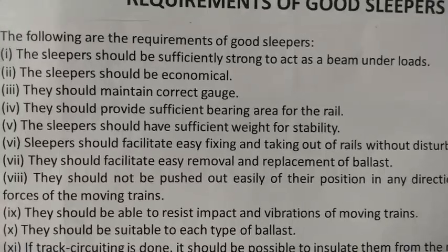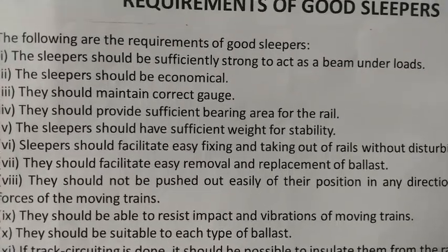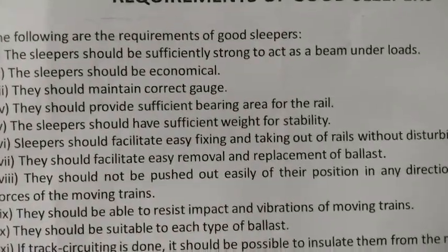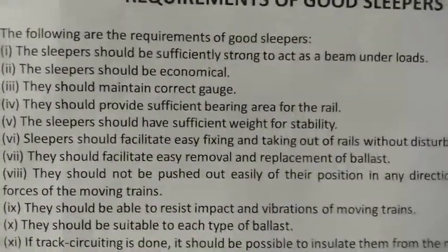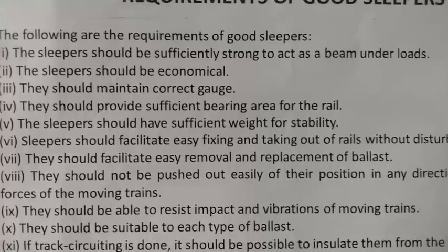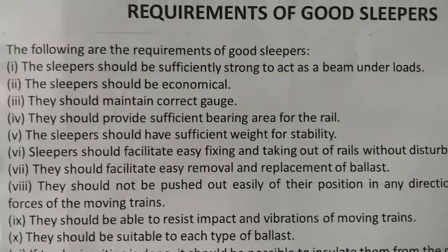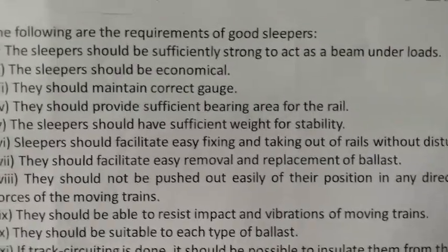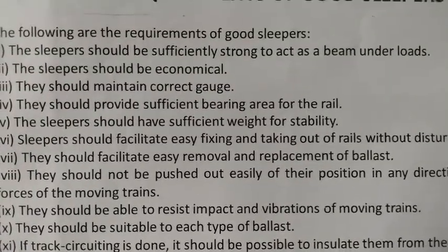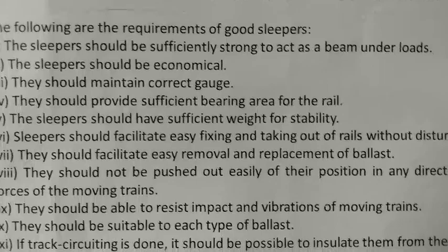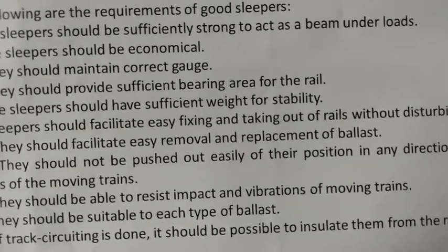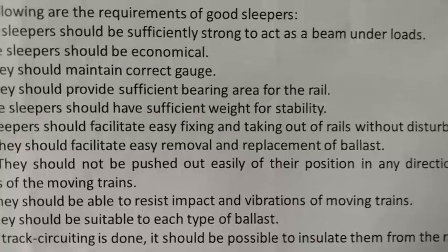Next, following are the requirements of good sleepers. The sleepers should be sufficiently strong to act as a beam under loads. It should resist the loads that are acting, both static and dynamic loads. Dynamic loads because of the movement of the train. It should also resist the vibrations caused by that movement. This sleeper should be economical. Economical in the sense that its initial cost and final cost should be minimum.